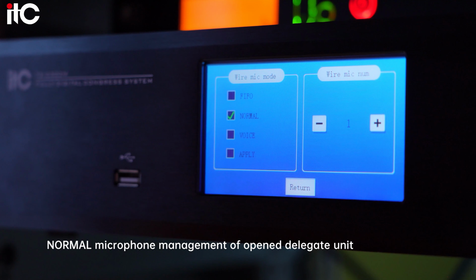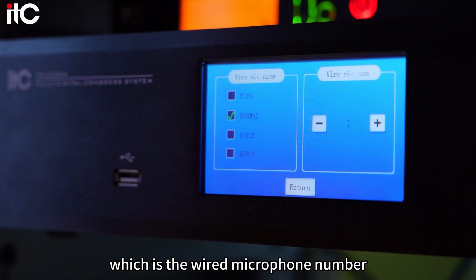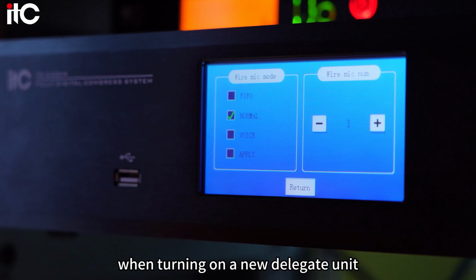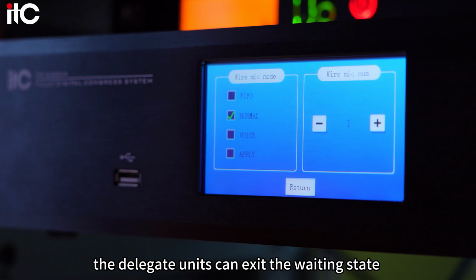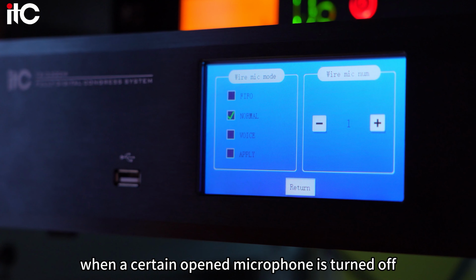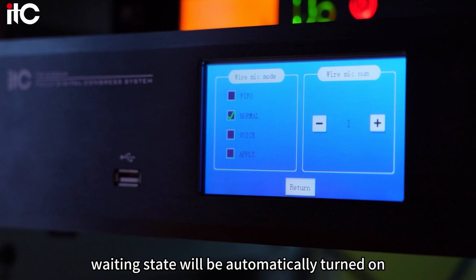Normal microphone management of open delegate unit. Waiting mechanism. When the number of opened microphones reaches n, which is the wired microphone number, it will enter waiting state when turning on a new delegate unit. And the maximum number of the waiting units is also n. The delegate units can exit the waiting state by pressing the microphone button. When a certain opened microphone is turned off, the first microphone in waiting state will be automatically turned on.